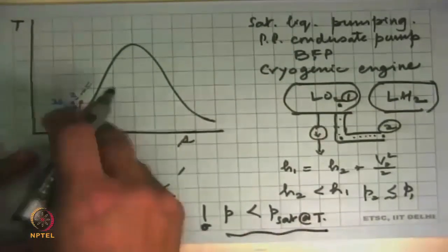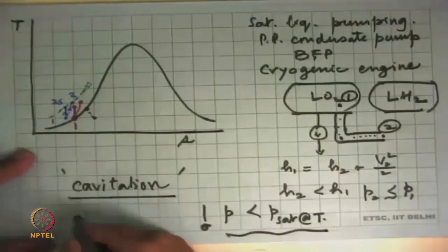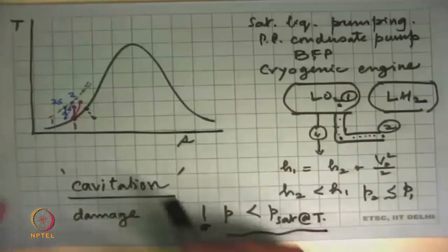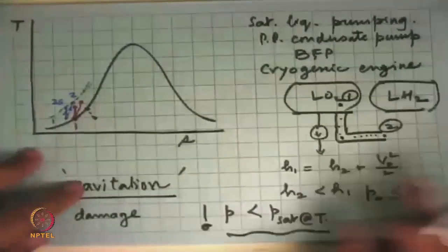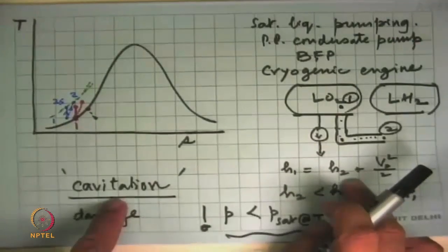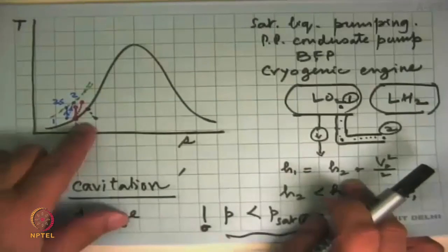but in our cases here, because when these bubbles form and break, they send out pressure waves and they do mechanical damage very badly, and in no time at all, the machine can get destroyed. So we would like to take care of that. But this is why the thermodynamics tells you that an important thing like cavitation actually happens, and what we need to do is what engineering is all about.